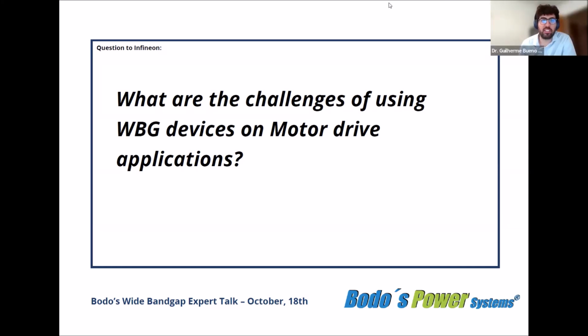Yeah, I think we already touched on some of the problems and challenges that we have here. I would just cite the 3 that for me are the most important. First is the bearing lifetime. We know that's going to be compromised by the switching frequency and also by the dV/dt that we are using. That's one of the reasons why Marco was talking about the limitation of 5 or 10 volts per nanosecond.